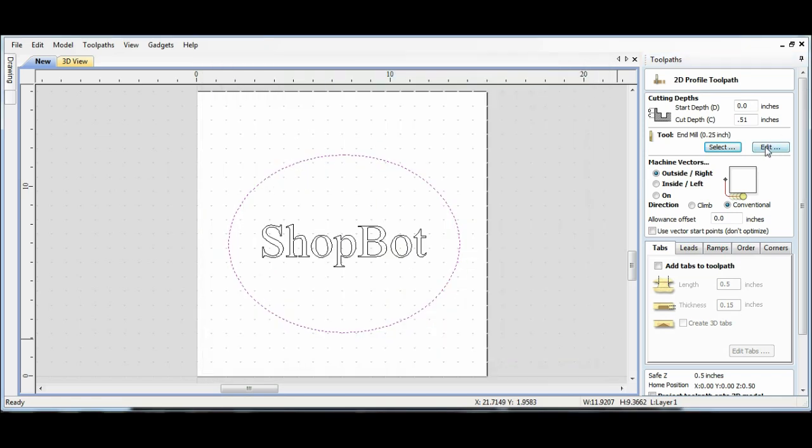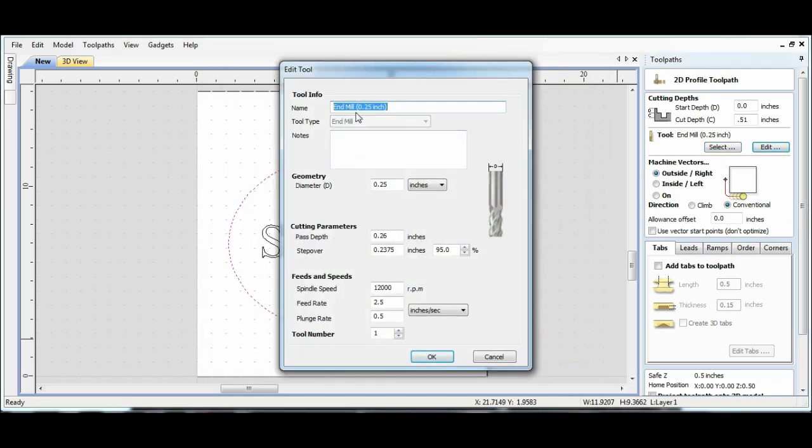Most of the time, with end mills, 1/4 inch end mills like this, or 1/2 inch end mills, it'll be the exact same, because if this was a 1/2 inch end mill, it would just be full size. There's no reason to have a 1/4 inch shank with a 1/2 inch cutter head on it. But when it comes to just a normal router bit that doesn't have these nice solid carbide spiral flutes, you might actually come across that.